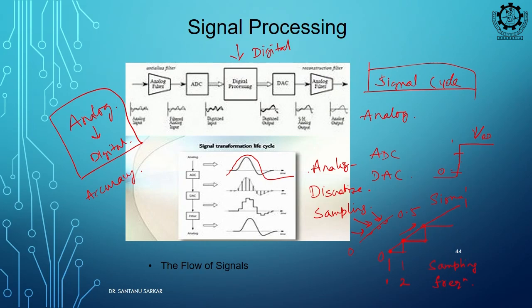Have you heard about Shannon's sampling theorem? Can you recall that? We can reconstruct a signal if we sample it at least twice the signal frequency, right. Suppose this is your signal, a sine wave, and suppose you are sampling just one data point. Can you reconstruct the sine wave?